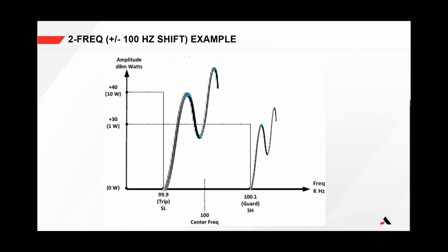For 2-frequency FSK, the transmit and receive frequency values programmed into the UPLC are never transmitted because they are the center frequency values, and only the center frequency plus or minus shift is used for 2-frequency. So if you wrongly try to measure the center frequency displayed on the front of the UPLC with a narrow band selective level meter, then you would be fooled into thinking the unit wasn't operating correctly.